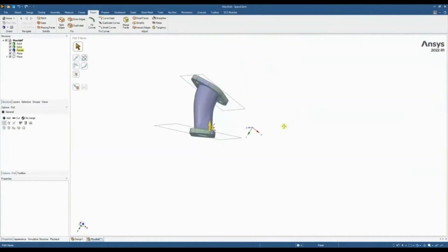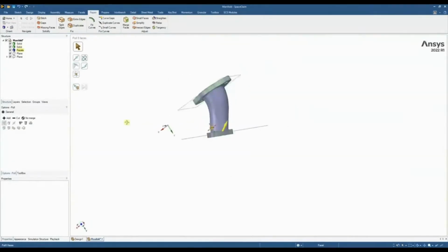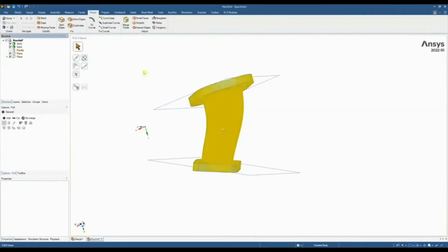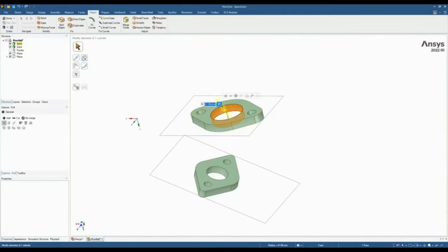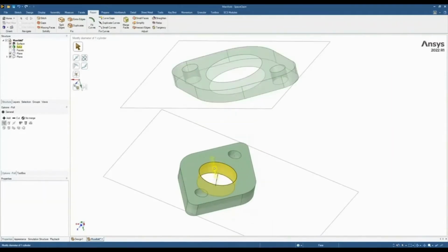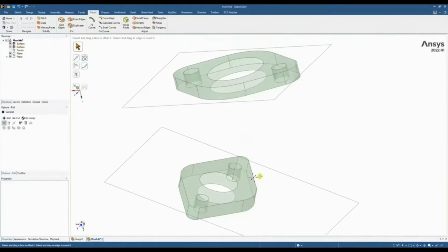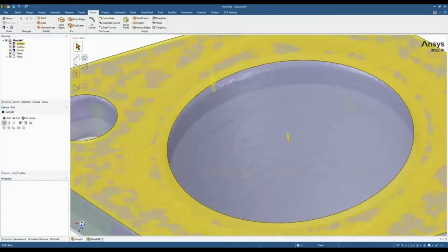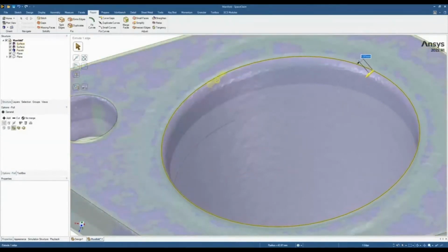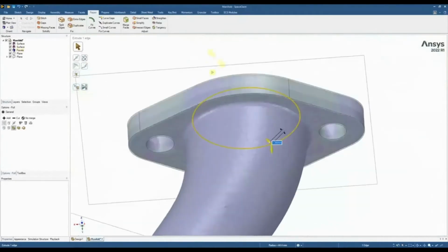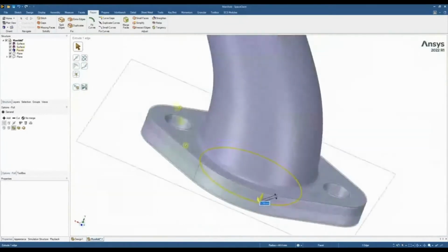So now we've got our two profiles. The next step is to join these areas up. So first of all, I'm going to hide the facet data, and this face here, there won't be a face here in the actual data, so I'm going to right click on it and delete it. This brings this back to surface data, and then I'm going to resize these areas, and I'm going to eyeball it here. Please be aware you can be a bit more precise than I'm being.